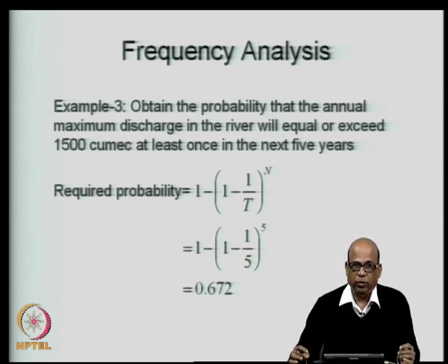By same population, I mean the watershed should not be disturbed during the period of record, nor should the gauge, either the rain gauge or the stream gauge that you are interested in, be shifted or changed, or major changes have taken place in the way of recording of the data.